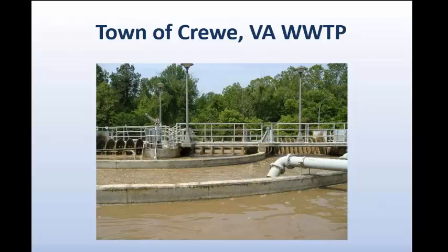All three channels are controlled by the same aeration equipment. There's one long shaft controlled by one motor and no independent control for the specific channels. All the control was manual. We had 3 different speed settings. You were either running on high, low, or off. And we do have 2 motors and 2 shafts. They're identical, and they're on opposite sides of the circular channels.